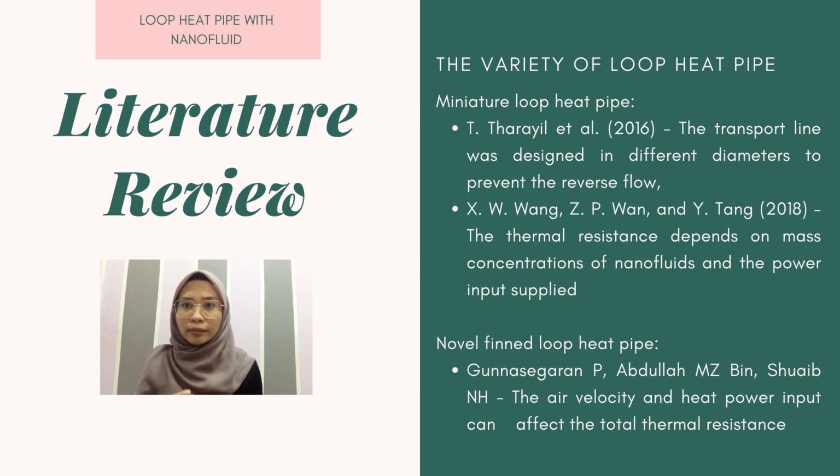For the novel fin loop heat pipe, other researchers state that the air velocity and heat power input can affect the total thermal resistance in a loop heat pipe. The result of the experiment states that increasing air velocity and heat input can influence the total thermal resistance to increase.